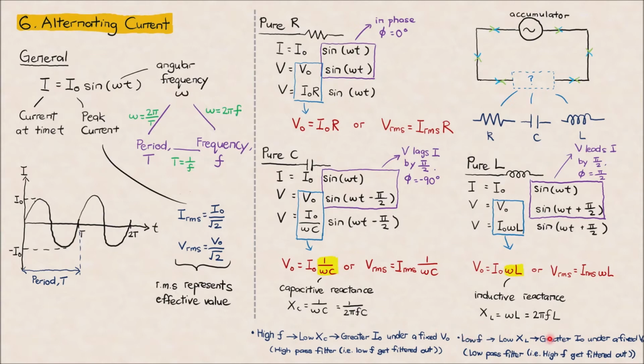So when low frequency generates a greater amount of current, we can say that the low frequency information passes through, because the low frequency actually generates a greater effect. It generates greater current. So we call this information managing to pass through. We call this kind of filter a low pass filter, because low frequency information generates greater current, whereas higher frequency generates low current. You can think of it as the information not getting through. The information does not bring out a very big effect.